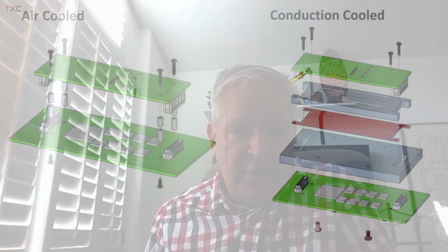And inherently, VNX Plus is a conduction cooled platform. And so we needed to have a QMC or a mezzanine IO that could support conduction cooling. So from the beginning, we designed this with very exacting requirements, if you will, for being able to support cooling the mezzanine through cooling structures in the carrier through conduction.